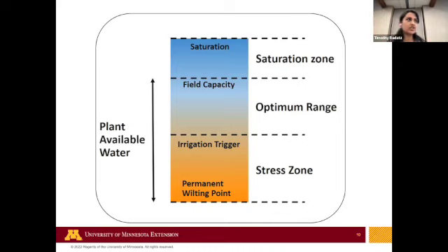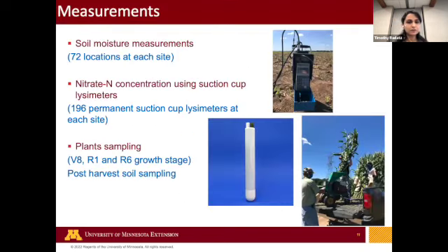That's our 100% irrigation. We have soil moisture sensors installed in all of our plots in the study. We monitor that soil moisture. We know the water holding capacity of our soil, so we know how much water is left in that zone. Based on that continuous soil water measurement, we decide our 100% irrigation. For our 75% and 50%, we reduce that amount to 75% and 50%. So that's how we carry out our irrigation treatments.